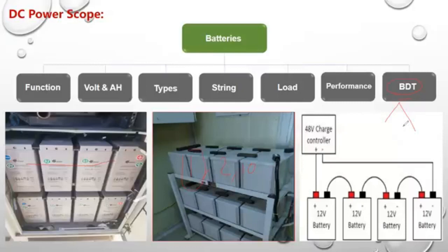After the backup batteries work, I start measuring the volts of the batteries compared to time. For example, after half an hour, I see what the battery measurements are.